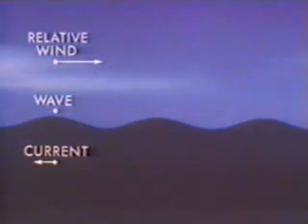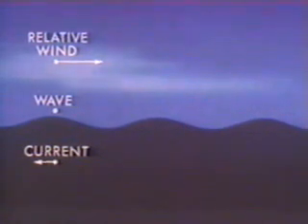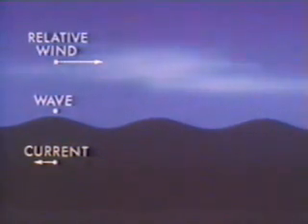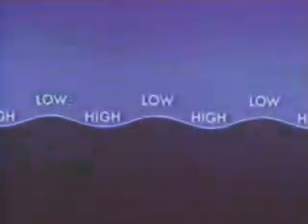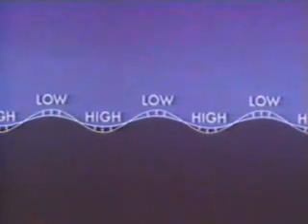It is the relative wind velocity which determines the pressure on the waves. The pressure will be low at the crests and high in the troughs. This distribution of pressure tends to increase the wave height, were it not for gravity and surface tension, which tend to flatten the waves. In this simplified view, if the pressure forces win, the waves will grow and we have instability. If gravity and surface tension win, the waves will decay and we have stability.